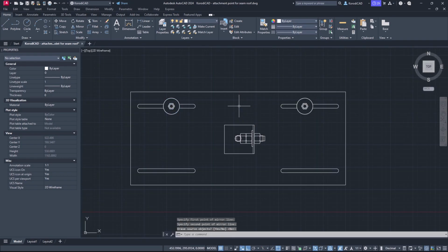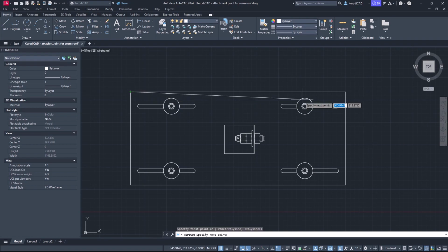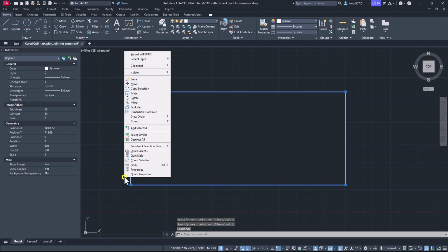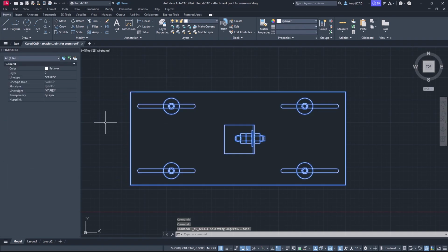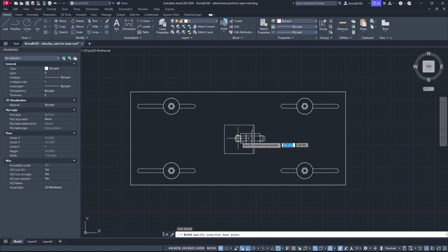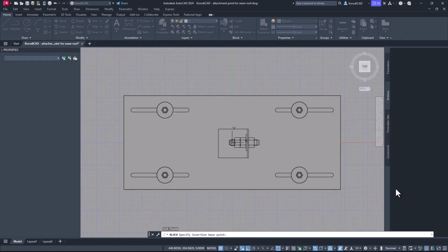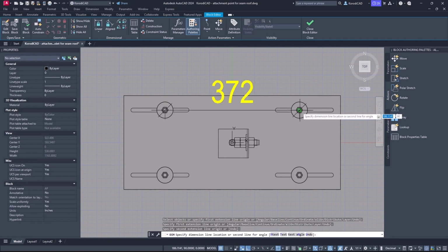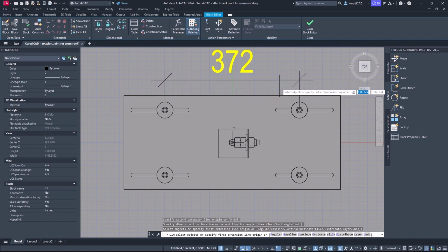First, the screws must be positioned so that they are horizontally and vertically symmetrical. For a more striking representation, masking can be used, but it is not necessarily required. Create a block. Specifying a pick point for this example is also not a requirement, but may require other editing tasks. The dimension also only performs a checking function. This can be omitted. If the block authoring palettes are not open, click this button to bring them up.